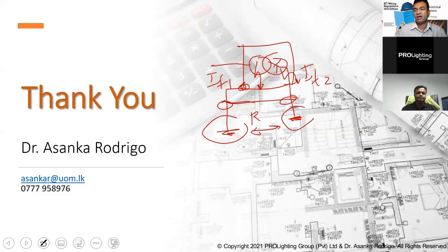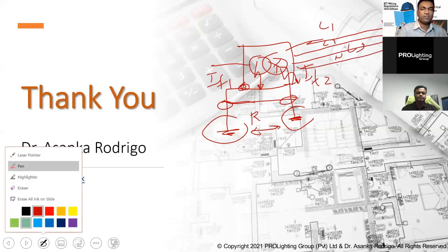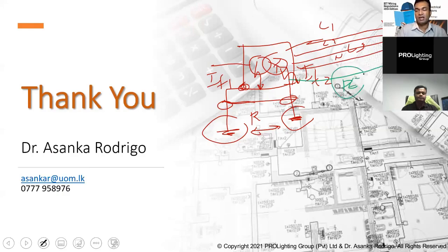Similarly, as you said, if you have your electrical equipment, you have, let's say, L1, L2, L3, and the neutral, and also you will have a PE conductor. That should be sized based on those calculations, as I said in the presentation slide, or you can use the simplified version, whichever way you do the calculation. Now, both of them are conductors, but for bonding there is a separate table to select the bonding conductor. But the circuit protective conductor and the earthing conductor, depending on the current you are handling, you have to size them and select them accordingly. Is it clear? Yes, sir, yes.